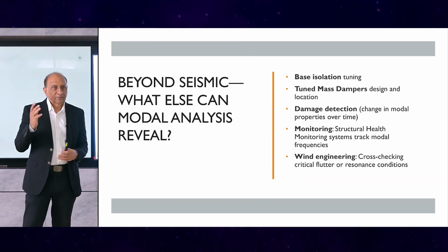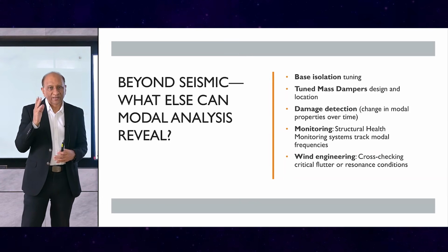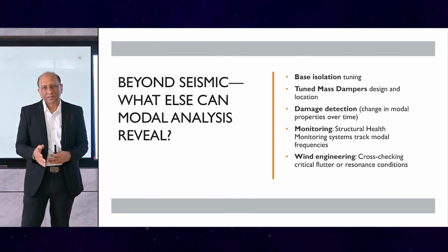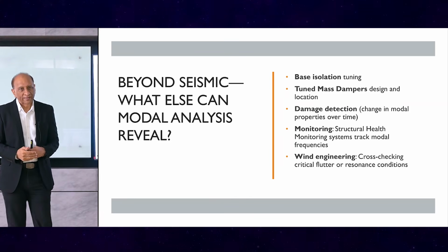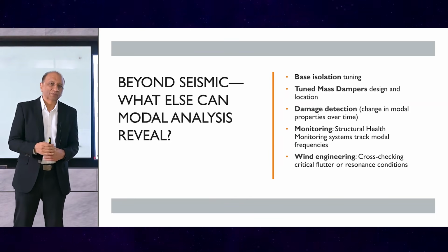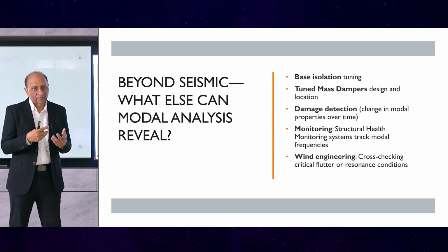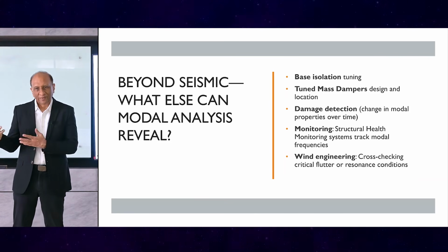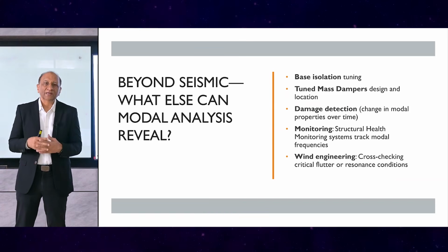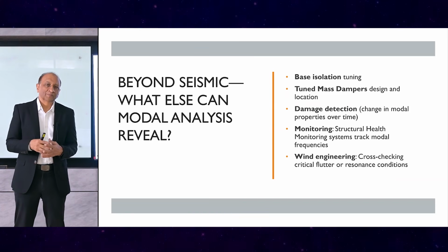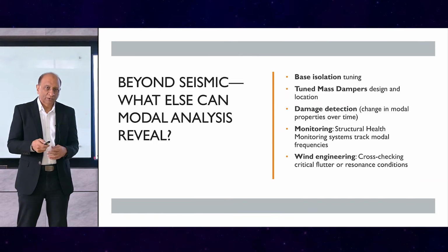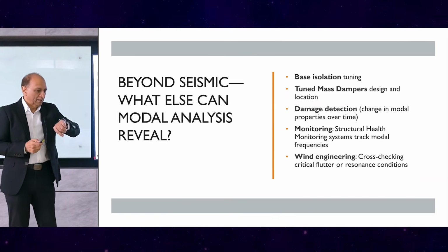Wind engineering has a very big relationship between the natural periods and the wind forces generated, especially the crosswind response. So the tuning of the wind mass dampers or whichever we attach is very much related to the natural periods.